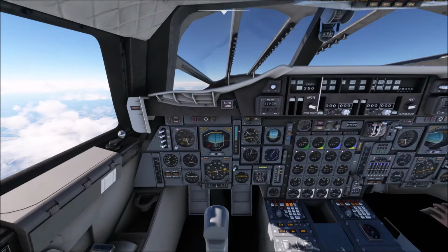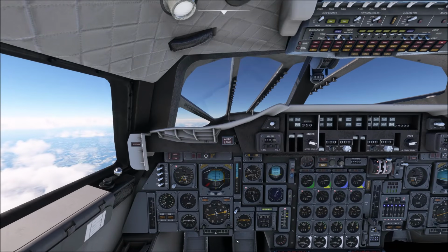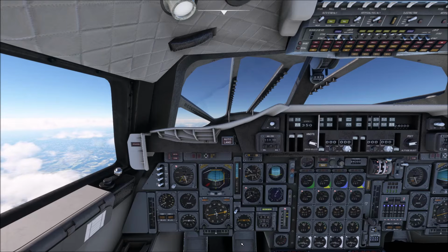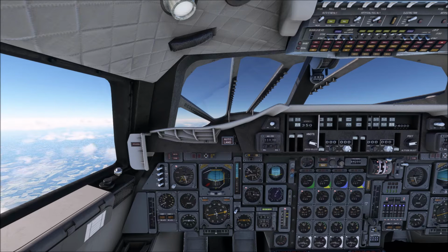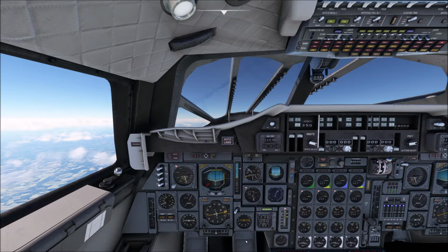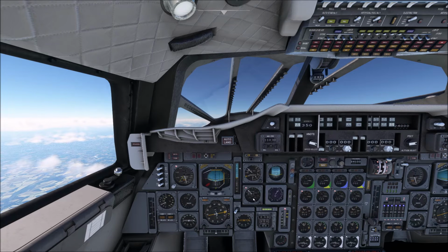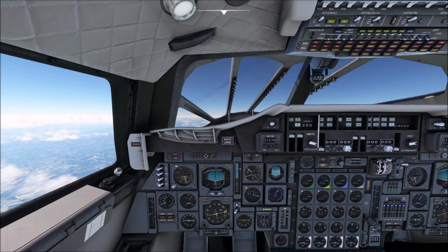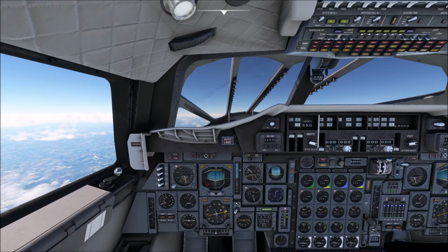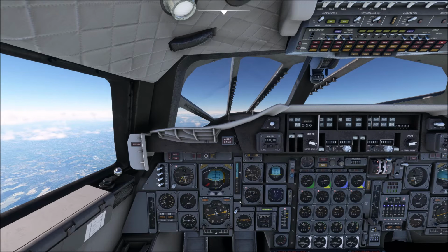See, we're not using afterburner, that's all switched off. Reheat lights are out. Almost there now, almost flight level 240. That's the levelling off altitude. Concorde would normally level off at 240, wait until it got over the Bristol Channel for sound reasons before it would then accelerate to supersonic. We're going to do it a little bit earlier.